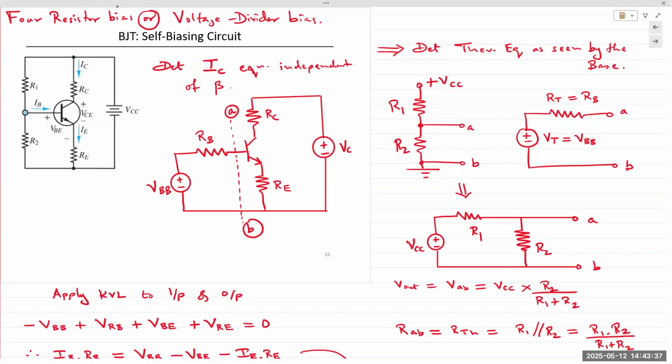So once you're done with today's class and you're reviewing this material, you can go back and take a look at the resistors and everything we used for that lab. Okay. All right, so 4-resistor bias. The name is kind of obvious. There are 4 resistors in the circuit, one at each of the BJT terminals, and an additional one, a 4th one at the base.